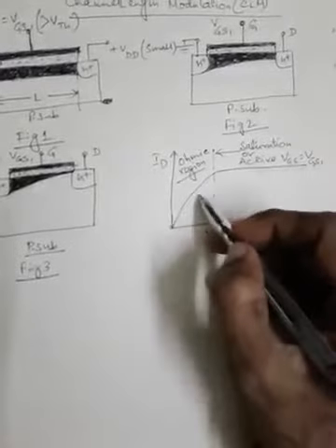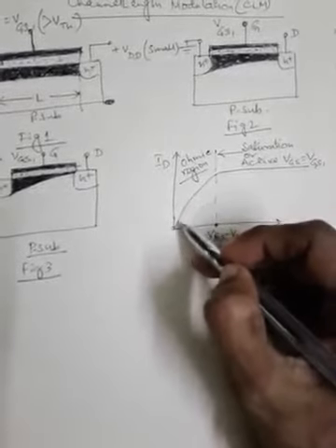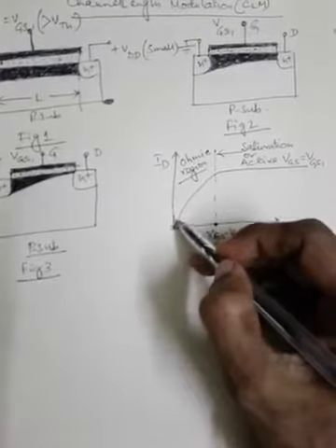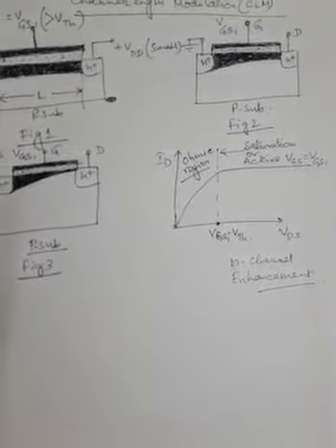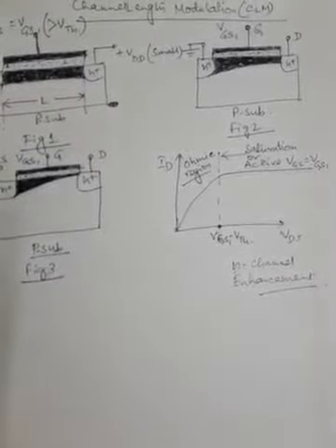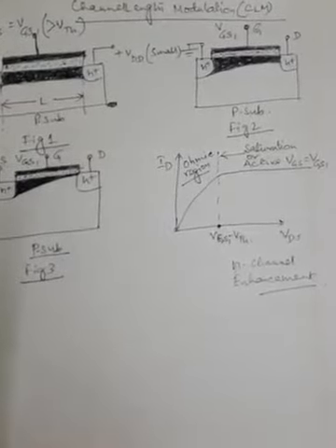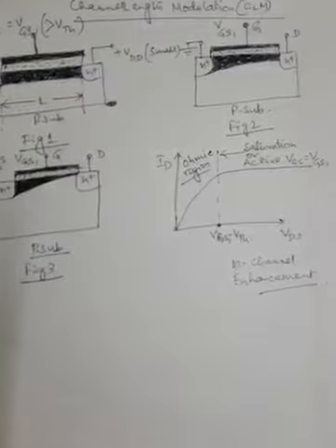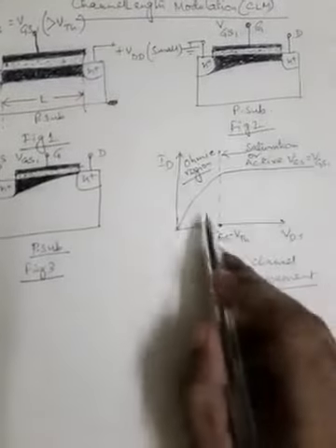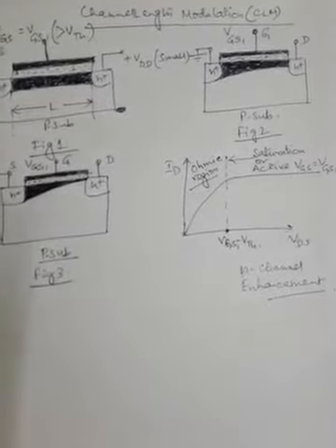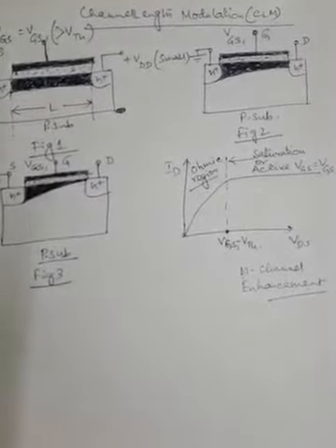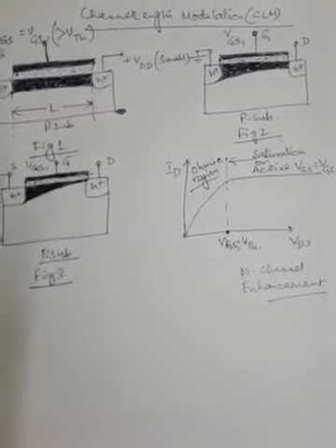If we do a piecewise linear approximation, that means if we segregate this region of the curve into small pieces, we can approximate that portion of the curve like a straight line, although it is a curve. So this is called the ohmic region or linear region, and within it the properties of linearity hold, and the MOSFET behaves like a resistor.